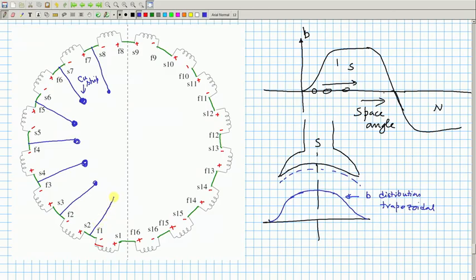This is the nicest part of this whole thing. Whoever first imagined this way it can be done, excellent, I mean, ideas. So you think in this way: from the junctions, I will drop down some wires here and terminate them on thick copper strips, each one. Are you getting? So it will be brought onto the same distance, like this. So these are the junctions of this series connected coils you have brought.